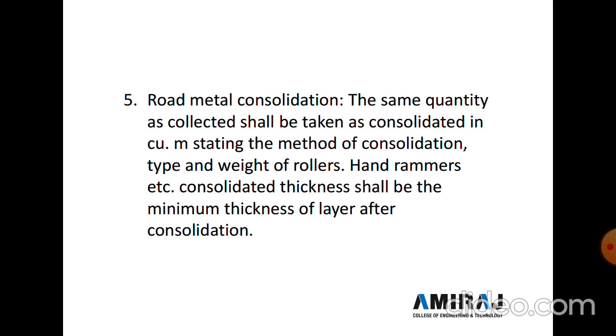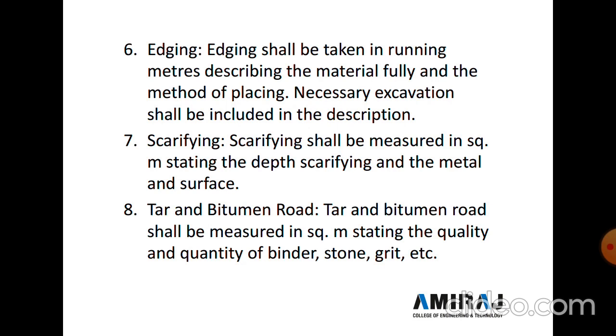Now next is edging. Edging shall be taken in running meters. Describe the material fully and the method of placing. Necessary excavation shall be included in the description. And the seventh point is scarifying. Scarifying shall be measured in square meters, stating the depth, scarifying the metal and the surface. And the eighth point is tar and bitumen road. Tar and bitumen road shall be measured in square meters, stating the quality and quantity of the binder, stone and grit, etc.